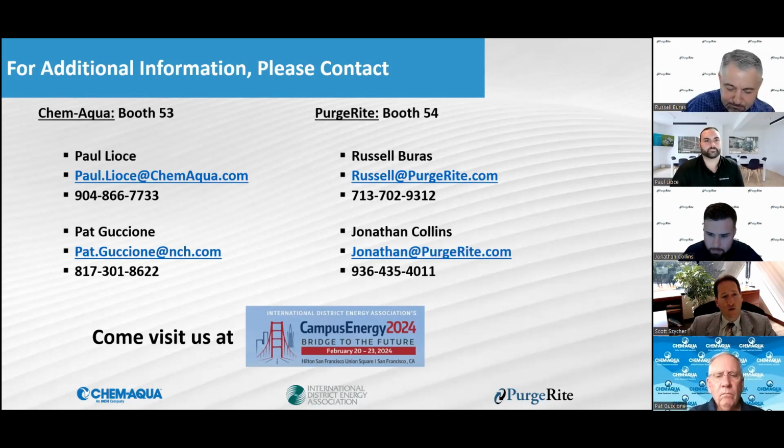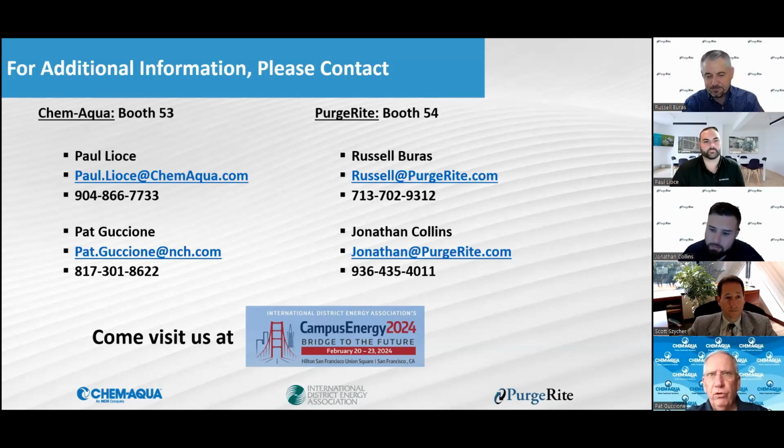Is there a role for vapor phase corrosion inhibitors? There is, especially in the layup portion of it. Vapor phase corrosion inhibitors or film forming amines are coming into use. They're especially effective where you have a lot of mixed metallurgies: yellow metals, aluminum, steel. Although the basic chemistry has been around for a long time, their use in closed systems, in passivation, or in system layup is still fairly new. But there is absolutely a role for them.